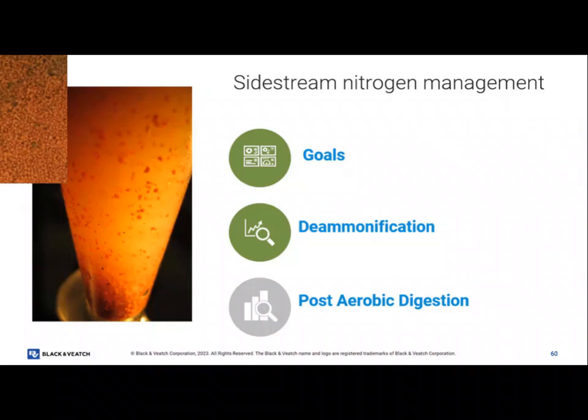And the reason I was able to get the 25 to 9 is because I did denitrification, right? I used carbon to denitrify. Let's say I'm out of carbon, but now I'm taking all of that 5, and now I'm at 14 milligrams per liter of nitrate going out, which means that I'm increasing in my anaerobic zone here. This is my selector zone for BioP. Now I have 5 more milligrams per liter of nitrate coming into it. That nitrate has a carbon demand associated with it, and that carbon demand gets fulfilled before the BioP works.